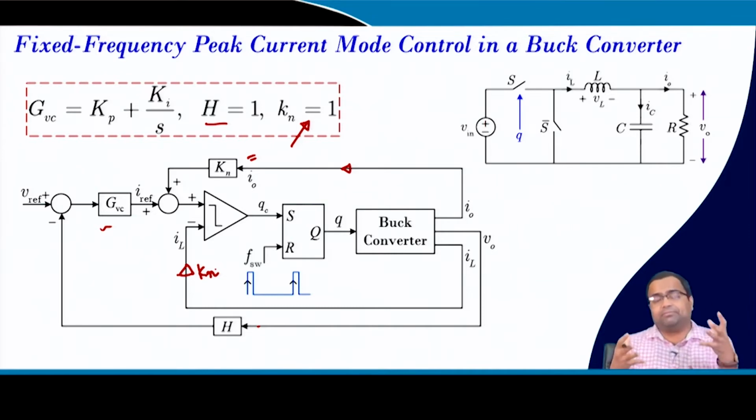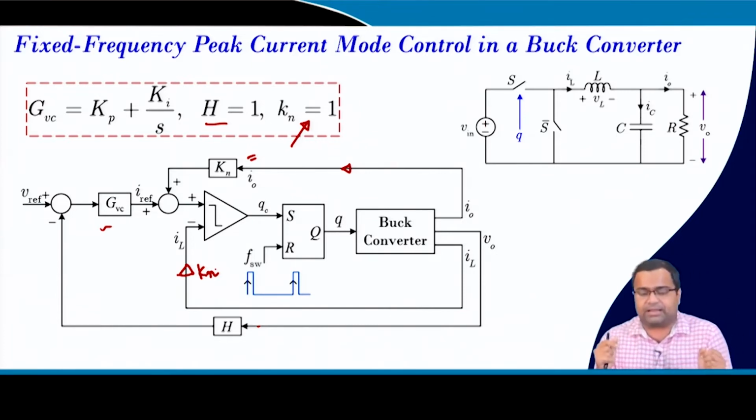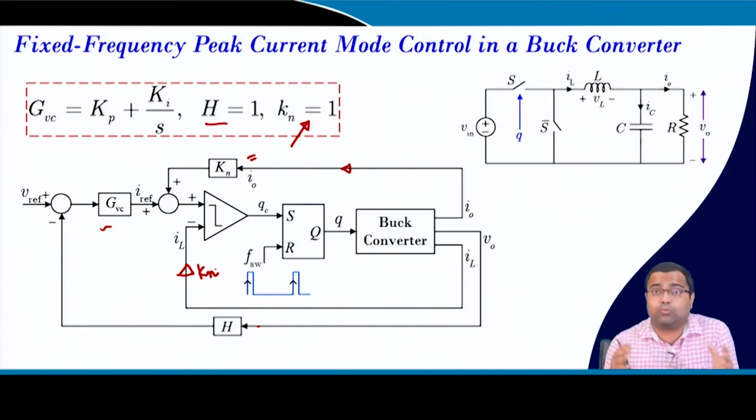Now, this question may come: this realization again requires sensing the load current. But suppose you are driving an LED using a buck converter, or you are driving a constant power load, or, for example in microgrid applications, we talk about droop control, where we sense load current because we want to adjust the droop. So, it is also available. Similarly, if we talk about LED driving, or battery charging, it does not require fast transient, so that does not come into the picture.